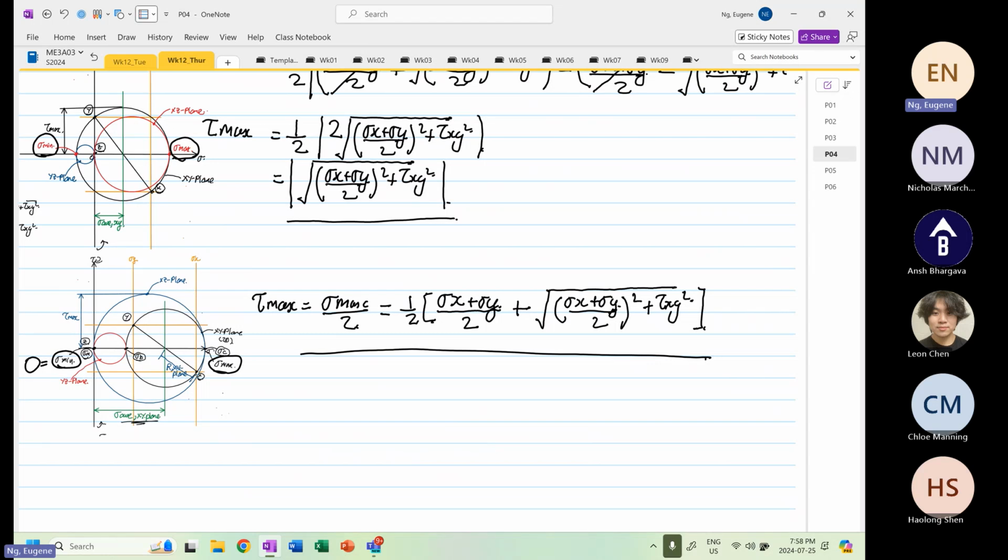You cannot do this in 2D. Impossible. I know textbooks only draw 2D and have fun. No, you have to construct the 3D Mohr circle, because in reality we're in a 3D world. I'm not saying that 2D is not important. You all learned how to draw Mohr circles using 2D, and 3D is just adding 2 more circles, right?